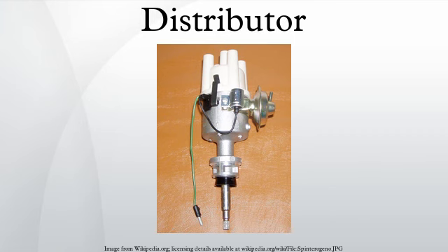4-stroke 1-cylinder engines can be built without a distributor, as in many lawnmowers. The spark plug is fired on every stroke, resulting in a wasted spark in the cylinder when on its exhaust stroke.